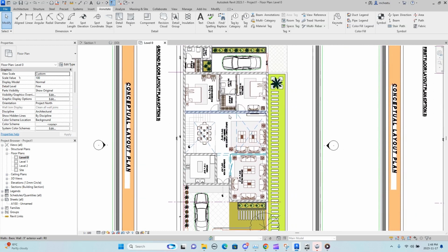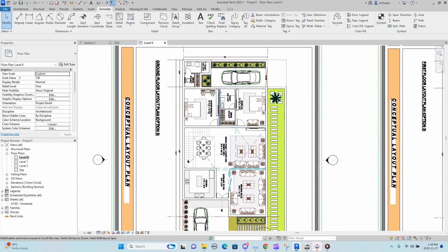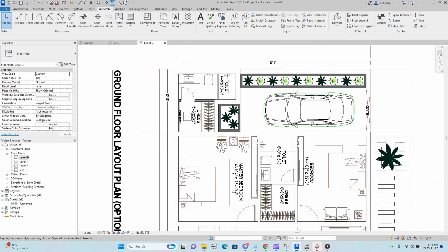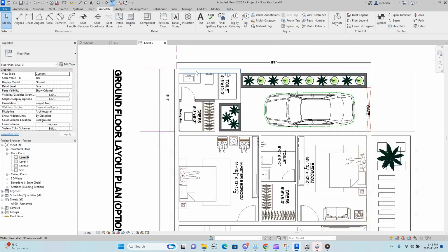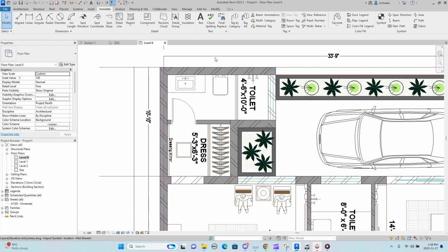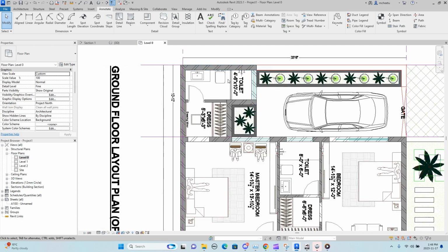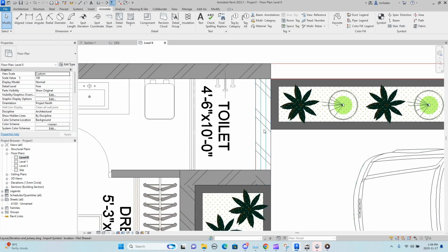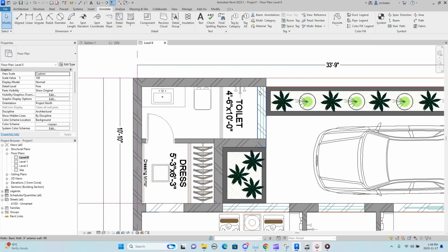Let's see what we can do with the windows. So right now we are not able to see the CAD plan below. So what we're gonna do is we have a couple of options here. So we can do realistic view, consistent color, shaded. Right now it's on hidden line. It means that you won't be seeing the lines which are underlaid. So we can go to wireframe, and that way we can see all the windows that are below the walls.